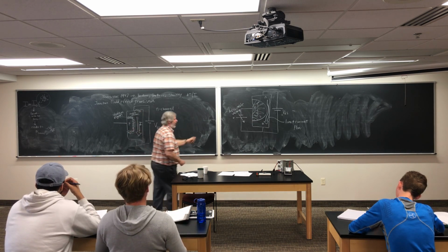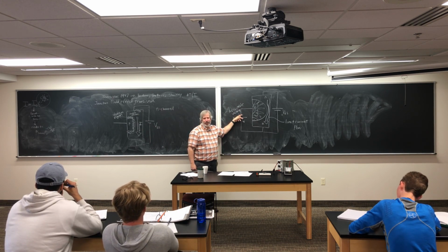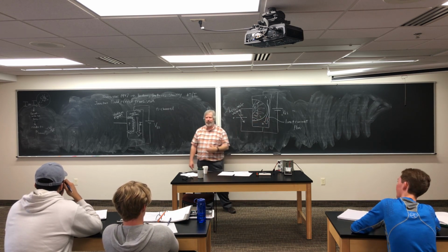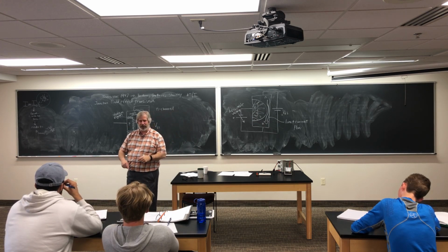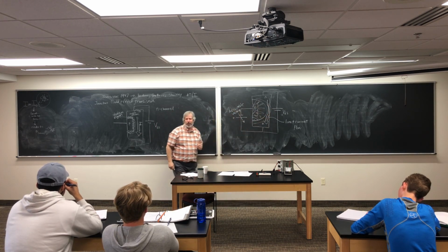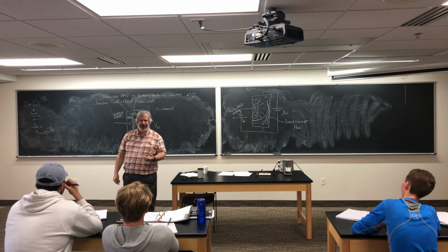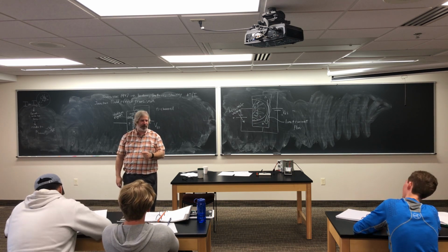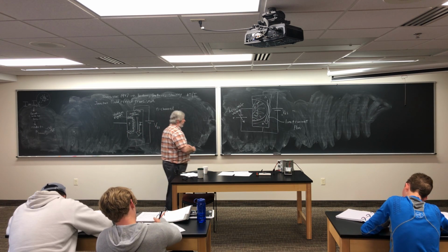So you don't have to have a battery with a knob here. You can have this fluctuating voltage any way you want, and you're going to control the current from a lot of current to a little current. You can actually even stop the current. Put enough reverse bias on there, you'll completely cut off. You have that depletion region where it just completely cuts off the current from being able to flow. Okay? So that's a very useful device to be able to rapidly change how much current you have flowing through something and control it electronically, and that's the transistor. Okay. So we'll talk more about it next time.